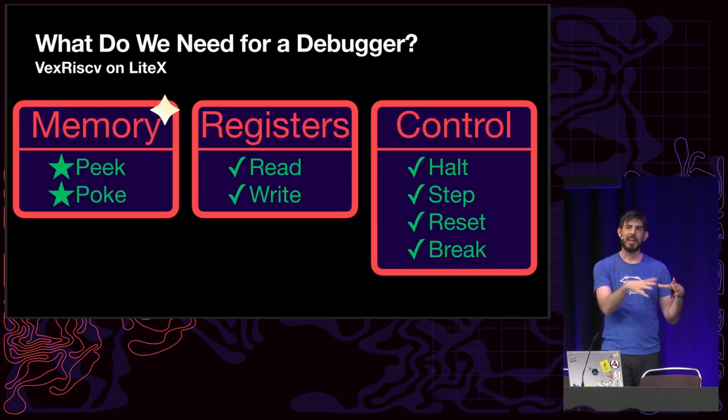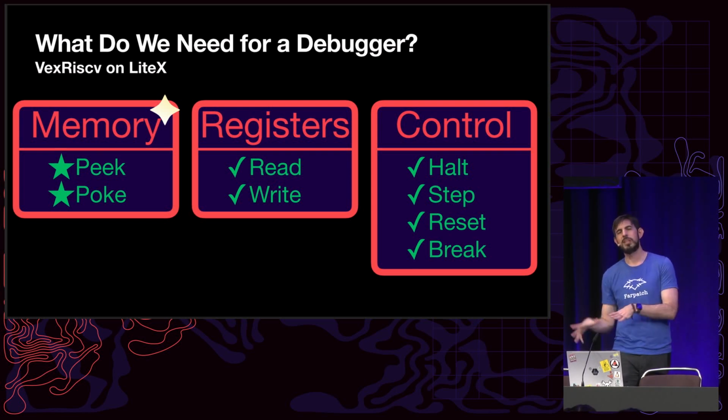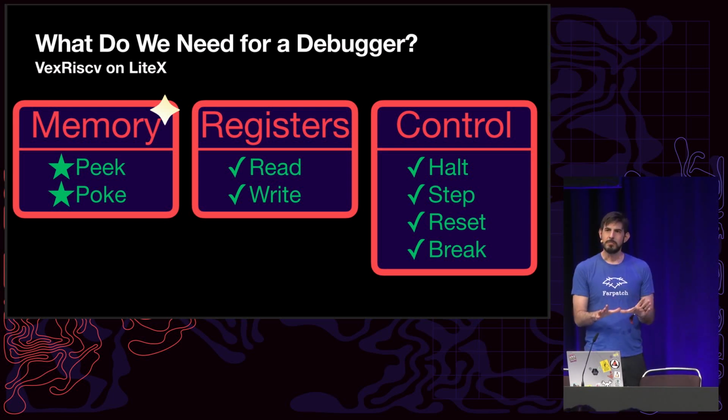So we had not only the ability to debug the CPU, but we could access memory while it was still running. By doing that, you could do lots of really cool things, the most famous of which is RTT, which gives you a serial console over your debug infrastructure for real-time access without halting the CPU. That's pretty cool. So that's how we did it on Fomu and Betrusted.